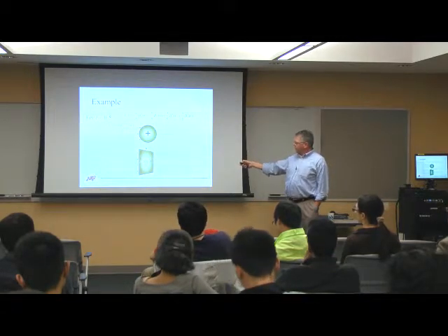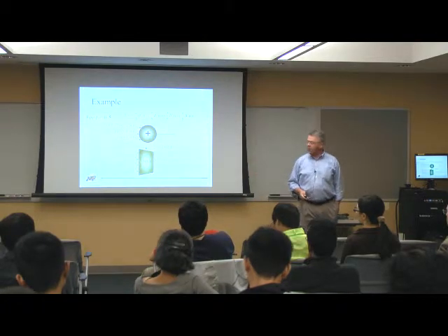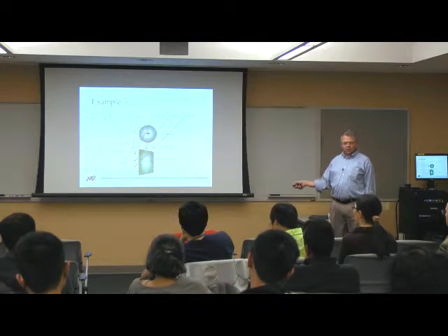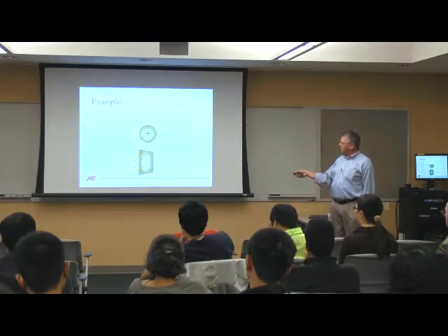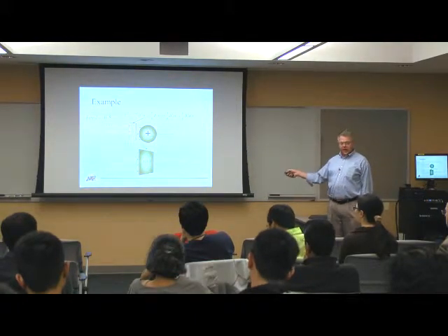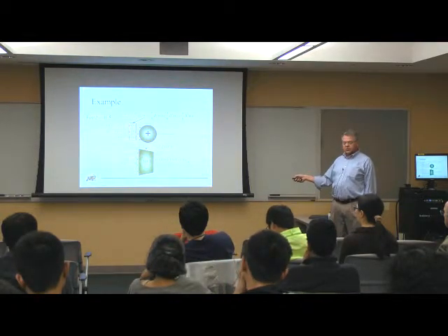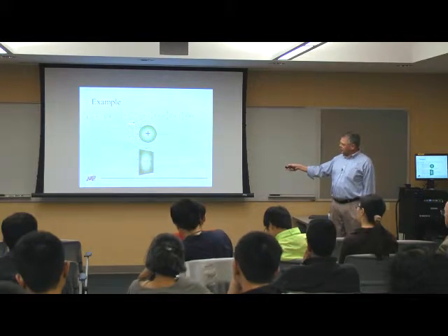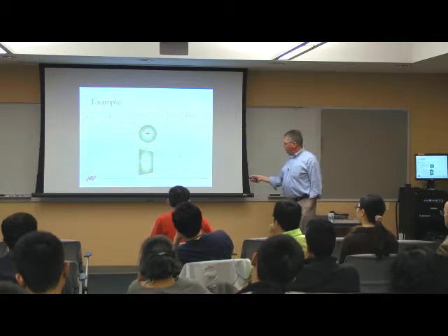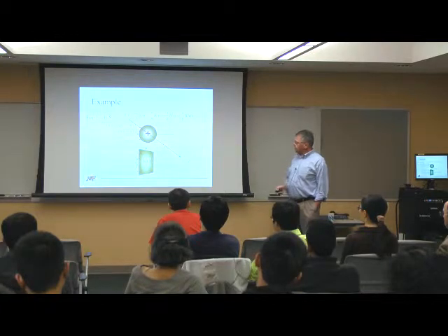I've got this simple adder here, and I've got this multiplexer, and I claim that this now implements that function. So down here, the inputs to the multiplexer are my Bernstein coefficients. You can see here the input t is right here, and I need 3 copies of that because I have 4 coefficients that I have to select here. So I have to have enough copies of the input to be able to select all 4 of those. The output is produced here. And then I just look and see how it steps through cycle by cycle.